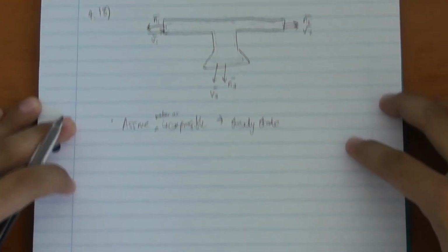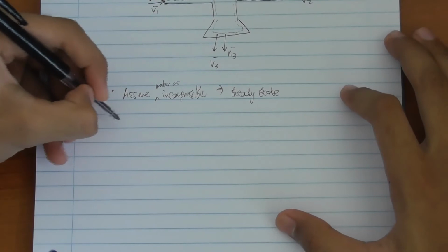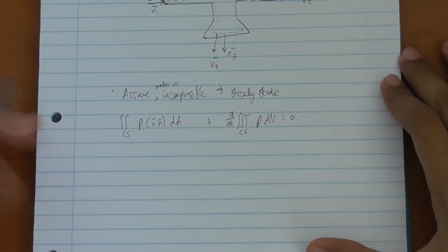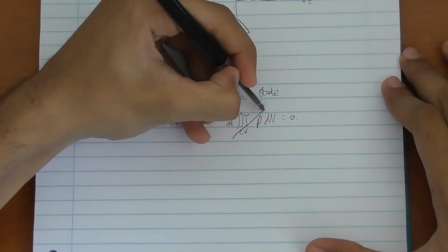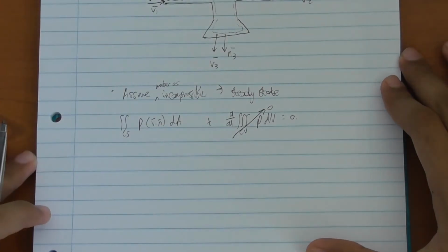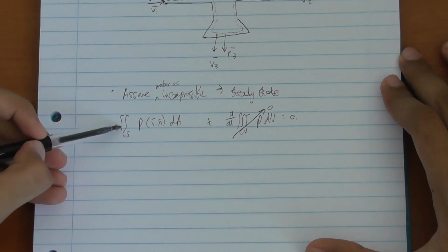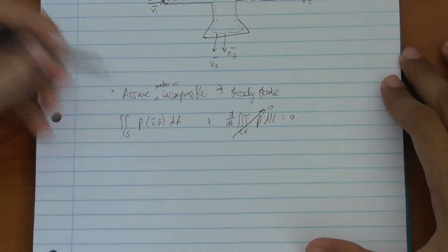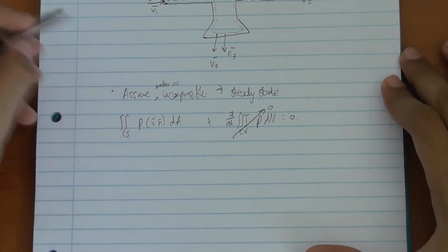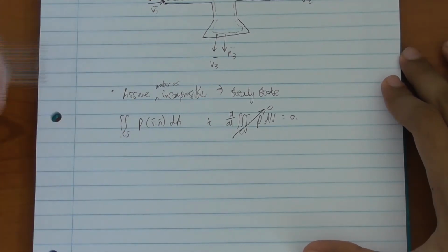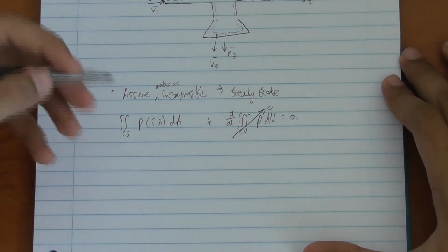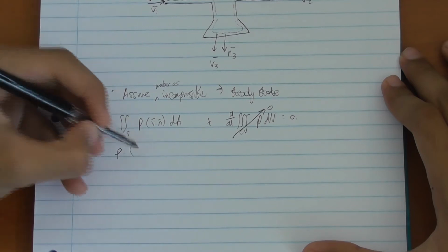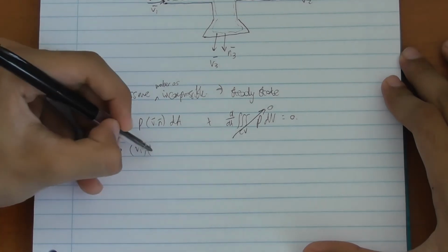Now, the good thing about this is that when you write out the continuity equation, which is the double integral, okay, the good thing about steady state means that this term can disappear entirely. So the only thing left for us to do now is to simply fill in this term. So let's begin doing that. I'm going to leave everything as variables for now and substitute in numbers later. It makes it a bit easier to calculate and we don't have to carry so many decimals. All right, so we're dealing with density of water multiplied by V1 multiplied by N1.